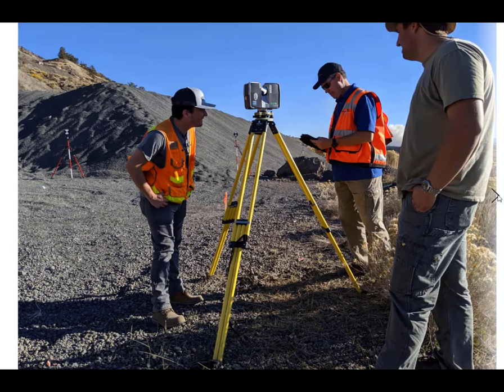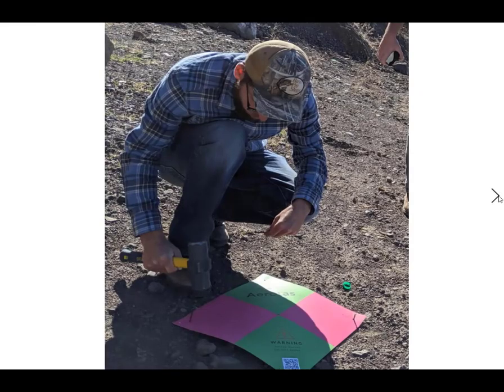Okay, the students rotated through operating the instruments, and I think they learned quite a little bit there. And here's something that I've come to enjoy very much, the biodegradable pre-mark. We typically would set a hub and put a tack there with the pre-mark and then position it, put a couple of just iron nails in to keep the wind from blowing it, and then you don't have to come back and pick them up. Within a couple of weeks, the colors have faded and the cardboard just biodegrades.